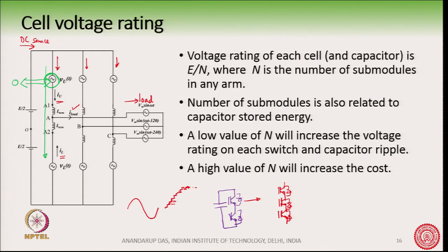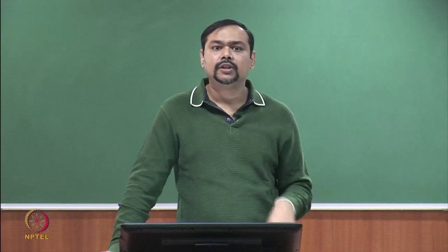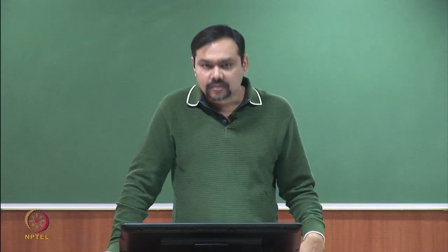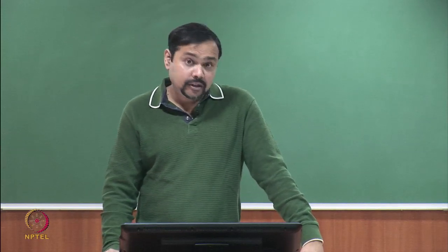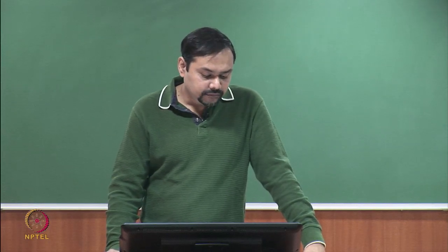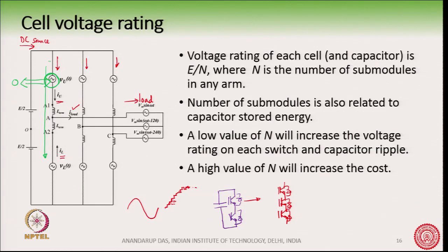Because the real power is flowing through the arms, the arm is losing or gaining energy, and we do not have a mechanism to compensate. That compensation mechanism is provided by the circulating current. We can find out how much the circulating current is, and it is predominantly DC, because the DC component is what makes sure that the energy over a period of time is 0.